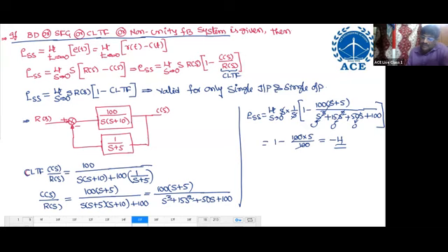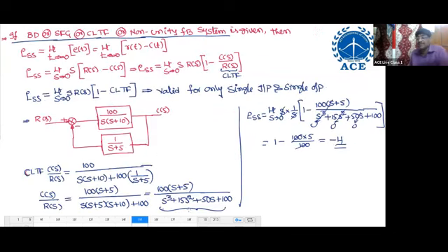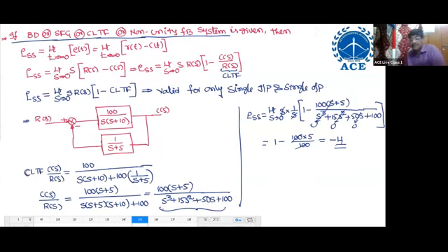So whenever they give a block diagram, it is a closed loop transfer function, stable only. It is 100% stable. You should check the stability of the closed loop system, not the G of S stability. Steady state errors are valid only for closed loop system stability. You have to check the closed loop stability, not for the G of S. Okay. So this is the steady state.